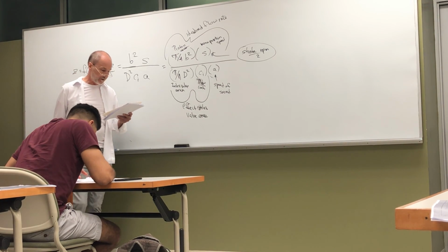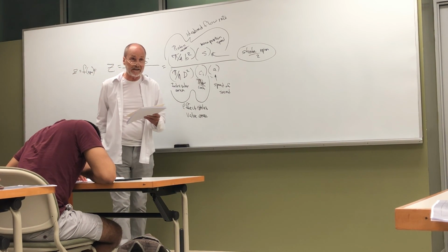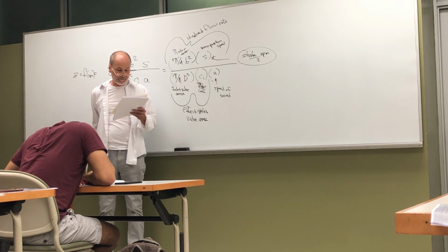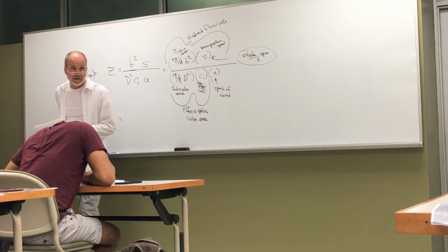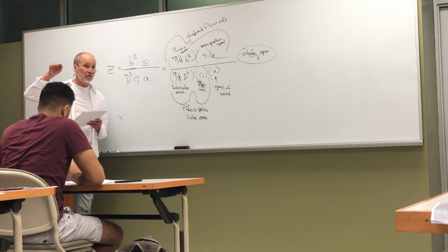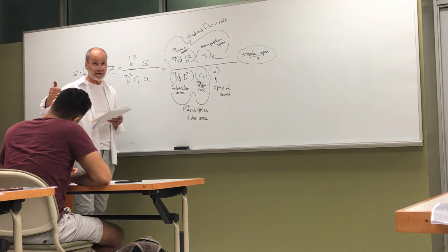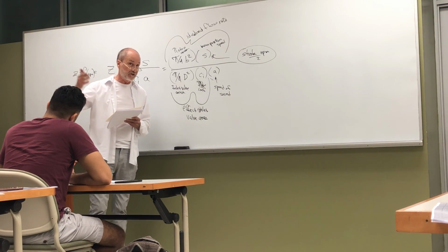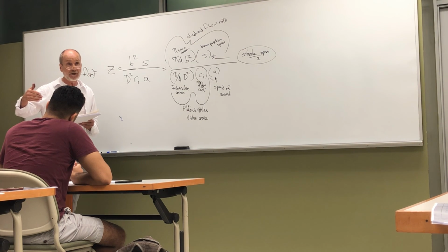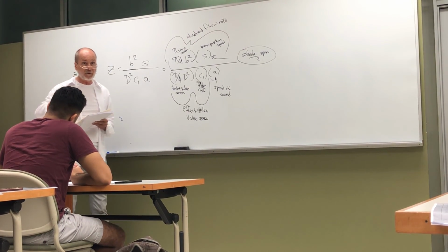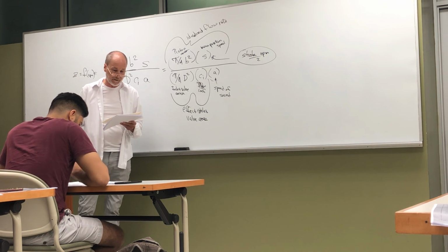Yep. We see a bunch of data, and we can see that as the Mach index number exceeds 0.5, the volumetric efficiency continues to drop. Which means at Mach index 0.5, we're going to begin to see a loss in horsepower because increasing the RPM, we're going to have a drop in torque, and eventually the percentage increase in RPM is not going to be sufficient to be larger than the drop in torque, and the horsepower begins to drop off.